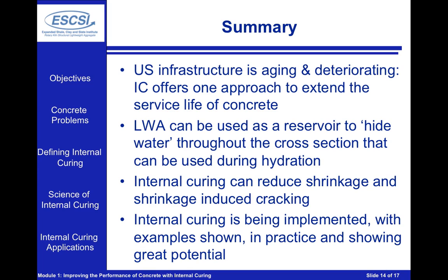Finally, what we've seen is there are several different groups that have been using internal curing on a full-scale basis. This internal curing is as simple as replacing a portion of the sand in our system with fine lightweight aggregate that's been pre-wetted. These examples have been shown, and in practice this is showing great potential.